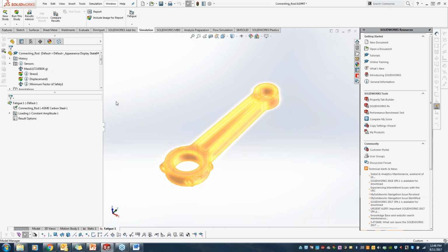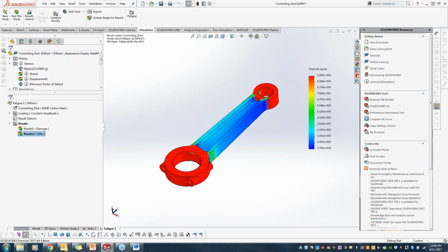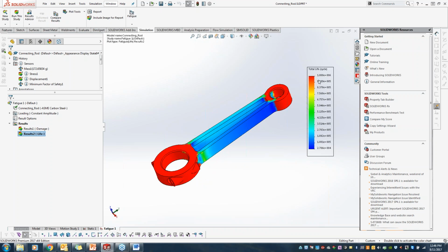We told the software two main pieces of information: what is the SN curve for this specific material, the relation between stress and life cycle, and what sort of stresses from which study are getting repeated, how many times, and in what sort of fashion. The rest is simply running the analysis. Look at the life. For 1 million cycles, anywhere with the red, we are happy. For the other region, the minimum is 2.7E4, which is the minimum life we get in our design.